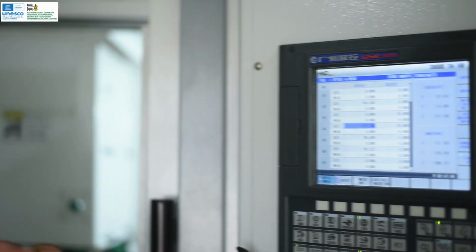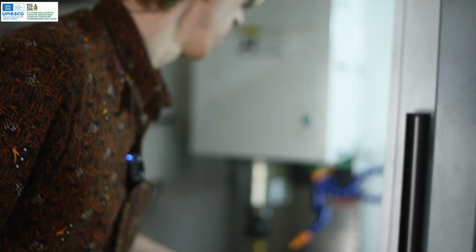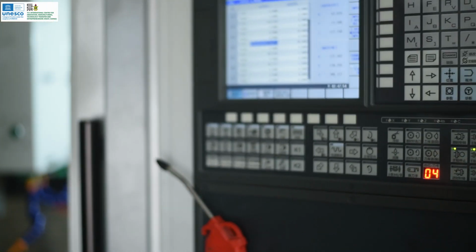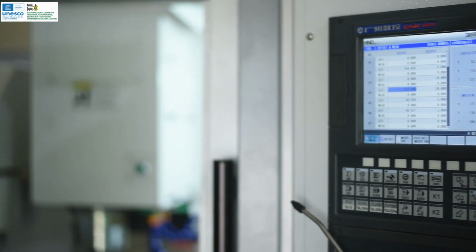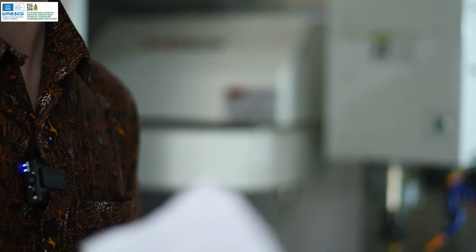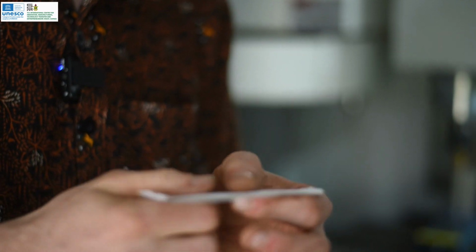If you wanted to be even more precise about this, you could get a pair of micrometers and measure your paper. And then instead of saying 0 when you input, you would say the thickness of that paper. We're going to be a little bit less precise in this case and skip that section. But if you wanted to put in a known thickness feeler gauge, you could also do that.